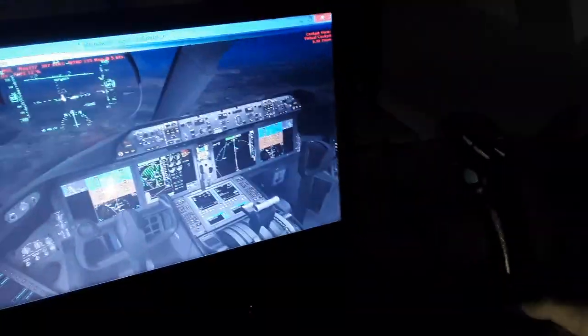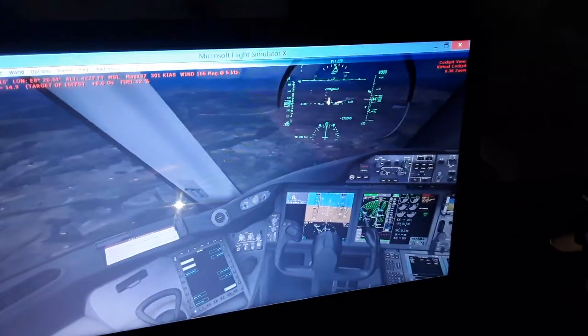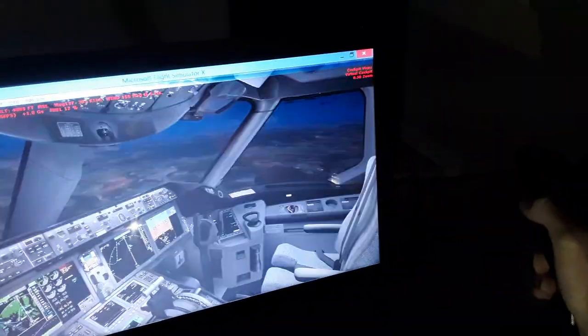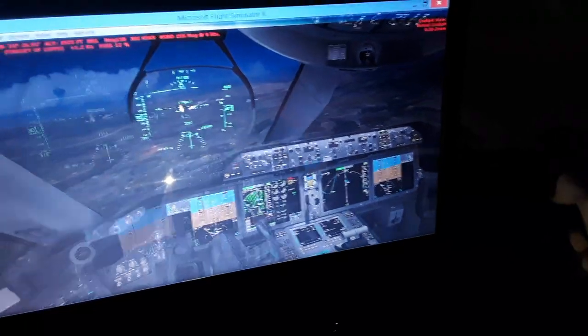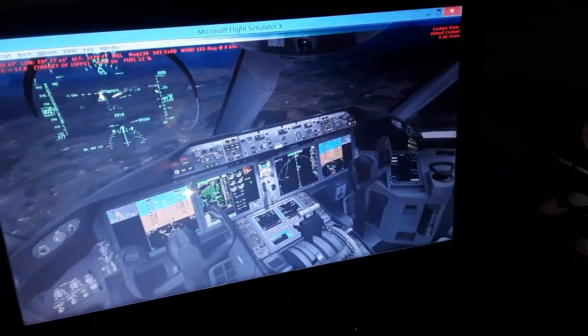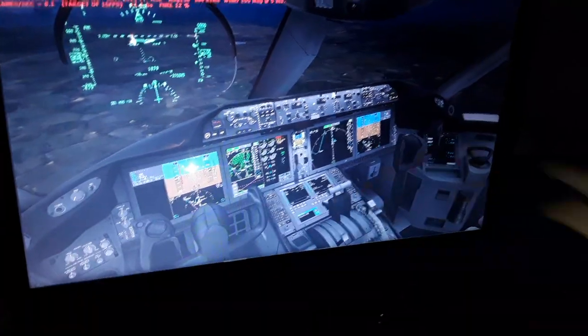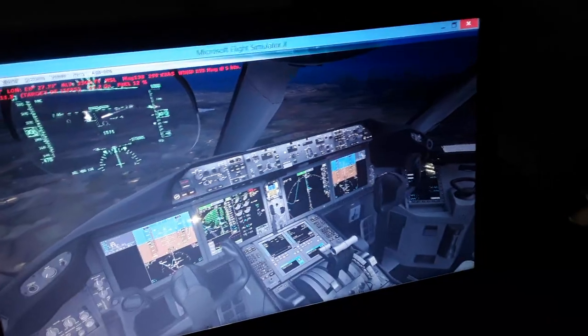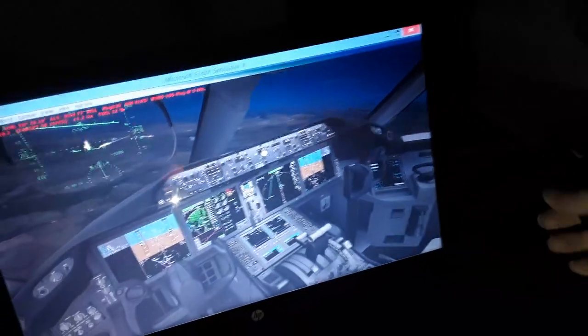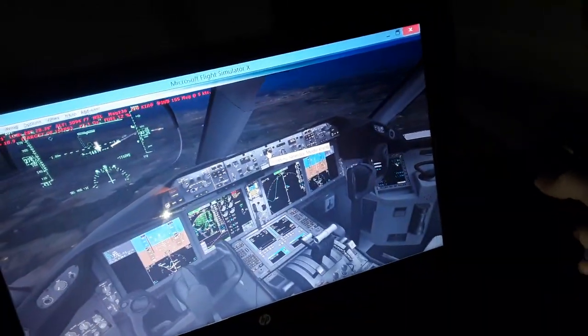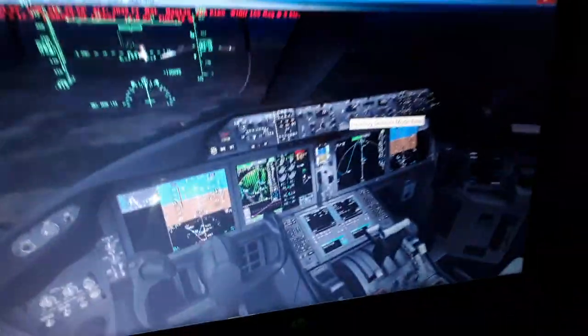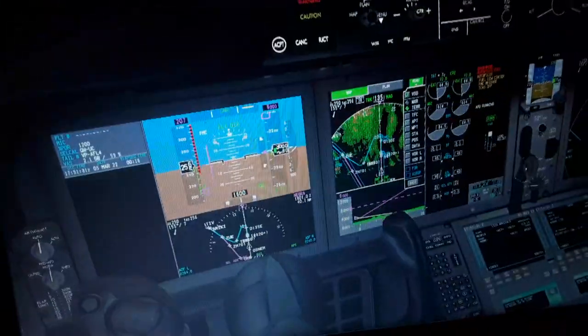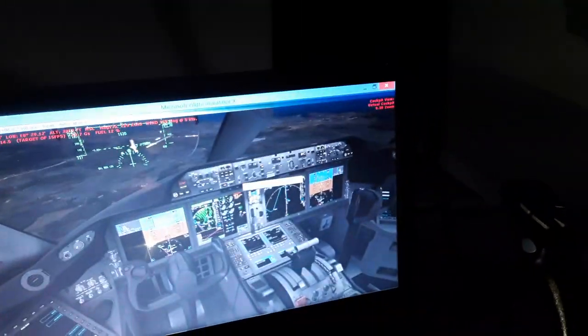More thrust needed. More airspeed. We have 1 more minute left. Also the flaps, start using the flaps down. A bit more idle thrust, as you can see. Align with the runway. We have some side wind over here, some wind gust. So we need to use cross controls, rudder pedals, ailerons and spoilers. So we have also the ILS localizer here, as you can see in the screen of information we need for approach and landing. So useful.